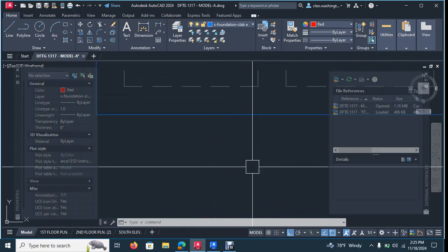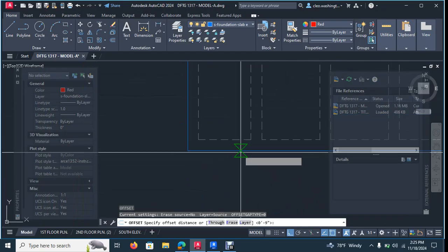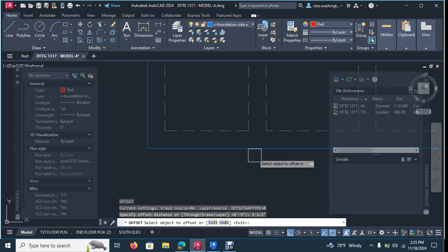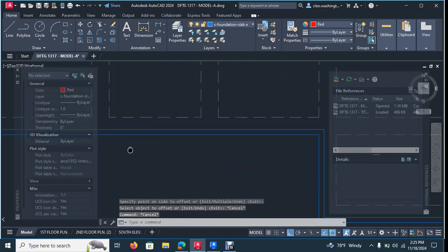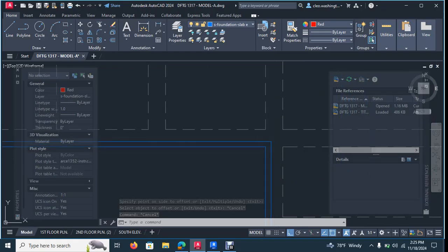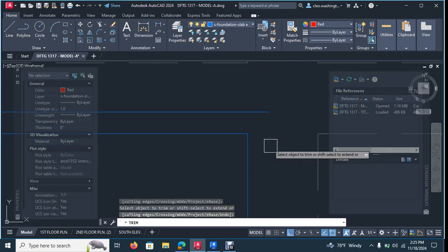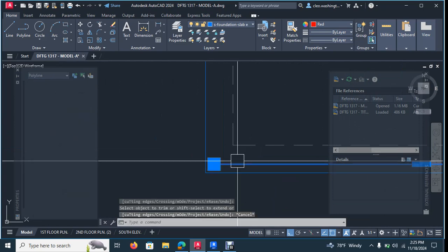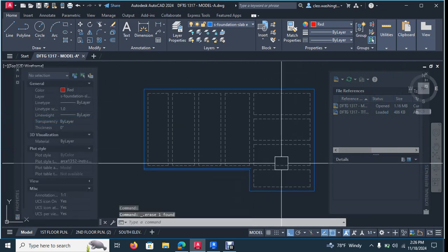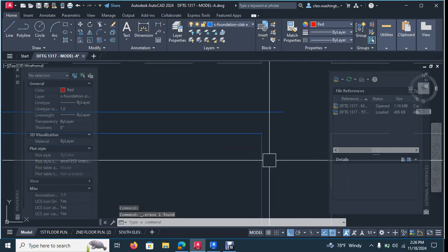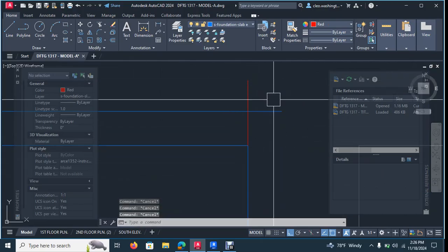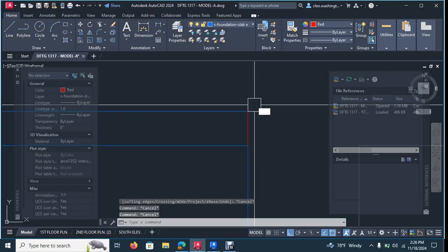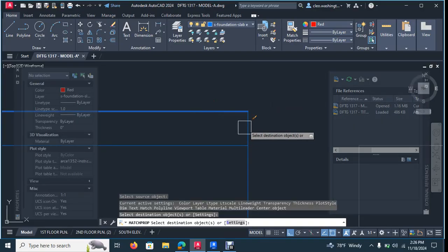So right here, you don't offset out. You go offset and then you go 5-1/2 inches. You're gonna offset this in just like that. Okay. So that's your brick ledge. You can leave it. I would actually come here and trim it up. And then just delete these because I think it just, yeah. And then draw a line right here. Trim it up. And that's the properties.